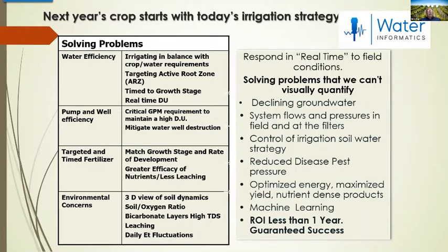You'll get more biofouling. But the other thing is that the well draws down from your standing water level to the pumping water level. Over time, because that pump's pumping at a very rapid pace, the speed of that water going into the perforations breaks it down, and a bicarbonate forms on that perforation. It'll actually seal your perforations. That will seal your well over time.